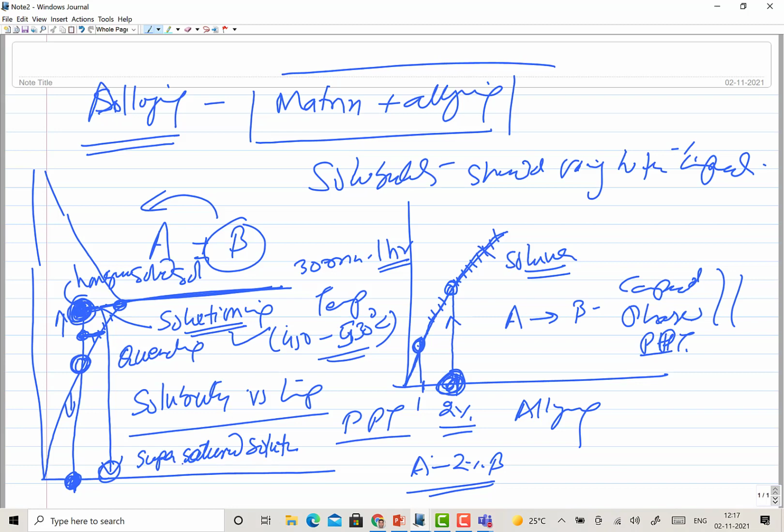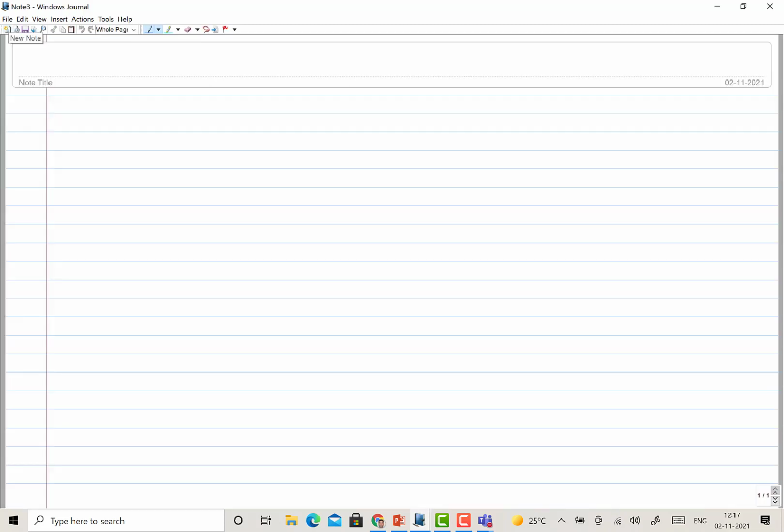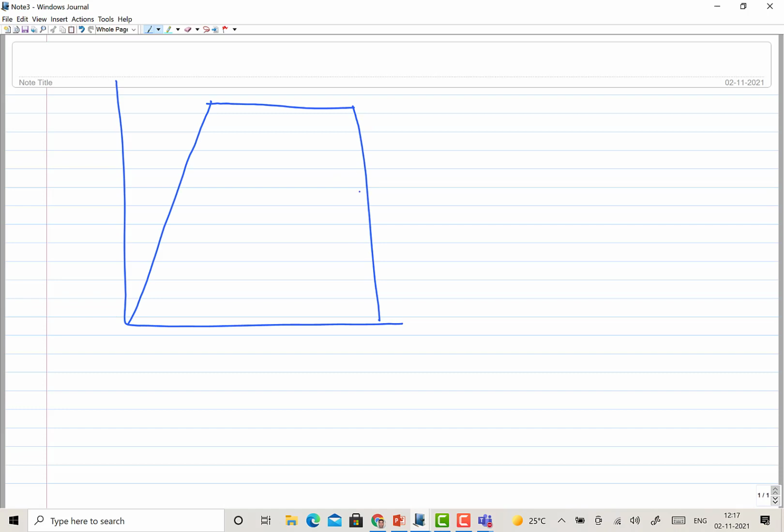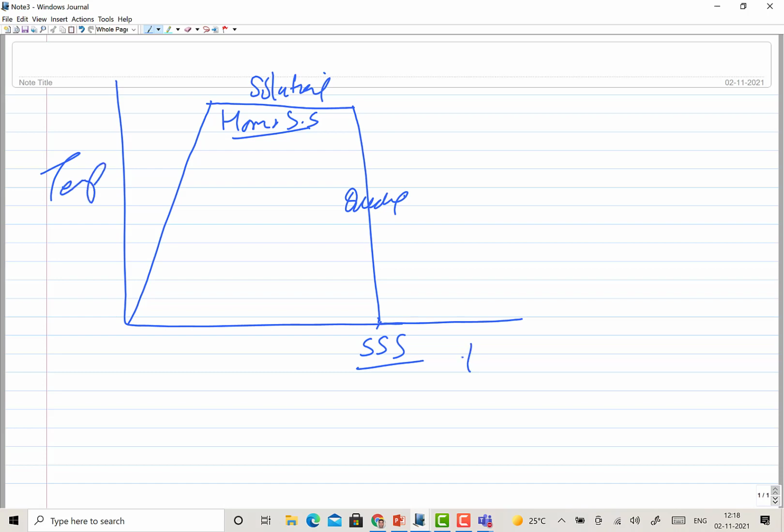Once the supersaturated solid solution has been formed, it is reheated. So the cycle we are following is heating to the high temperature, solutionizing, followed by rapid cooling. So this is the quenching phase, this is the solutionizing stage. Okay, and after quenching to room temperature, here you get the supersaturated solid solution, and here you get the homogeneous solid solution. The difference is that the homogeneous solid solution may be undersaturated because of the high temperature exposure. On the y-axis we have temperature and on the x-axis we have time.